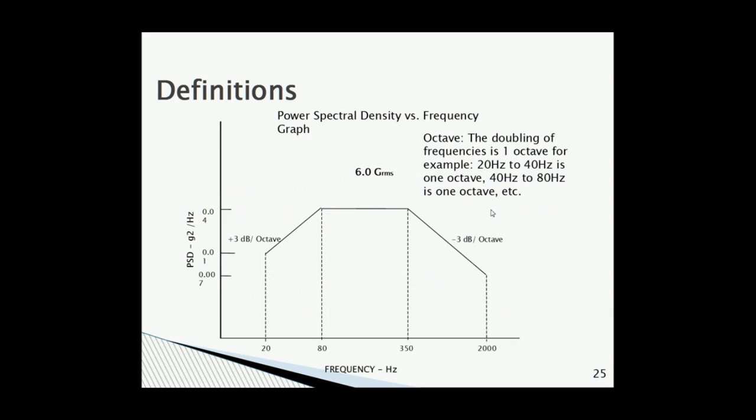Okay, let's go ahead and look at this graph. Should look familiar to you. Here is a random vibration graph. Now, random vibration, unlike sine, does not occur at a single frequency at a time. It occurs at multiple frequency points simultaneously, and the amplitude and the phase of these vibration points at each frequency is random. Now, this is more representative of the real world.